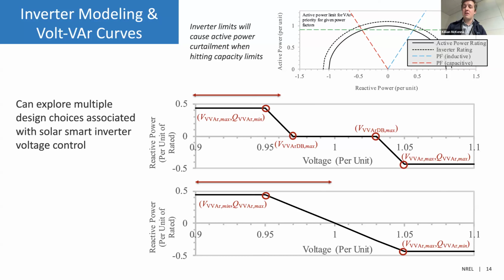But part of our work here was developing optimal power flow models of three-phase imbalanced systems and being able to model optimal volt-VAR curves, which is a capability that we developed but haven't utilized as much in terms of operation. Next slide.